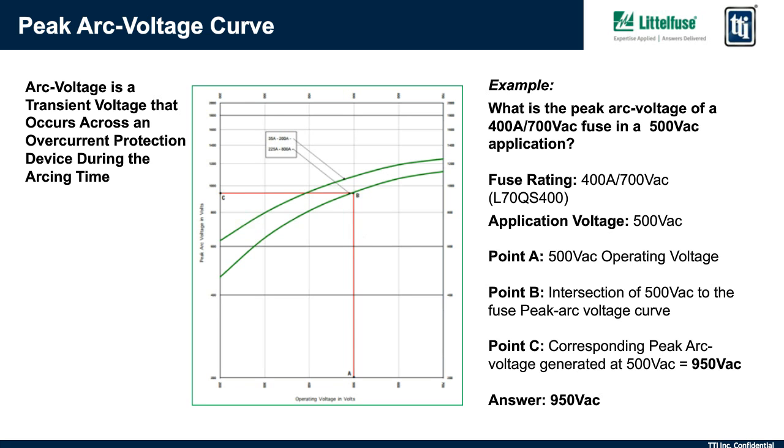During the arcing process, a combination of the inductive energy in the system and the fuse quickly shutting off the current causes a peak instantaneous arc voltage to appear across the fuse terminals that is often greater than the system voltage. This arc voltage generated inside the high-speed fuse can also appear across power semiconductor devices that are connected downstream of the fuse as an instantaneous reverse voltage.